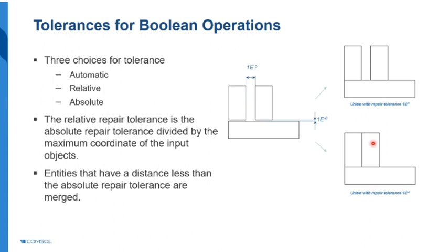Another thing you need to consider whenever you are using any imported geometry in COMSOL is to see where the geometry is located. If it is very far from the origin, meaning it is making some order of magnitude difference, just bring that geometry as close as possible to the origin itself. For that, COMSOL has various commands, and you can directly move the entire geometry to certain points. That is also possible.